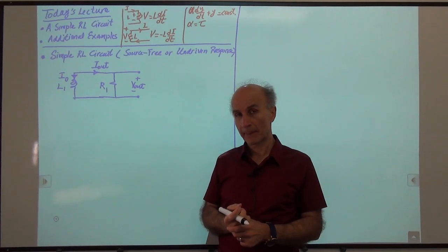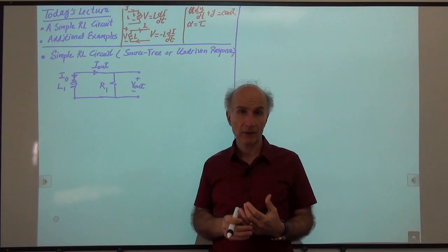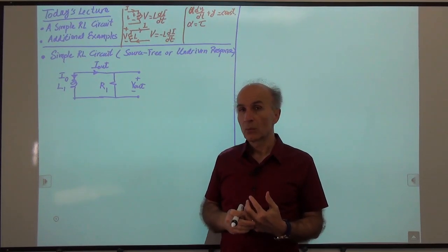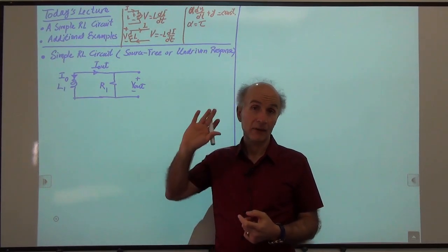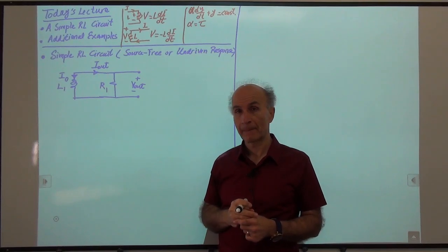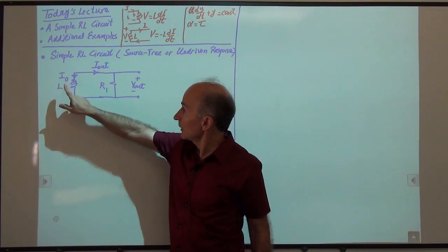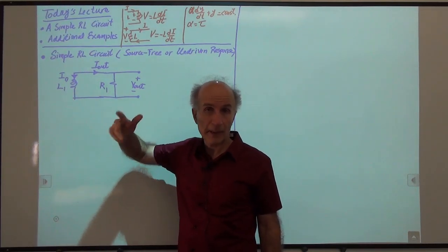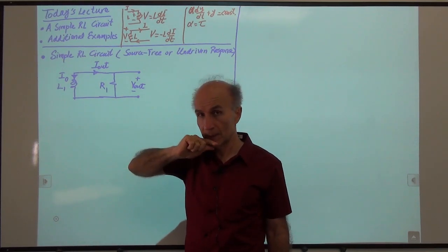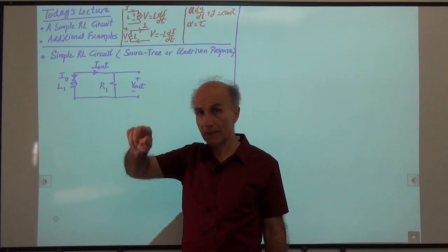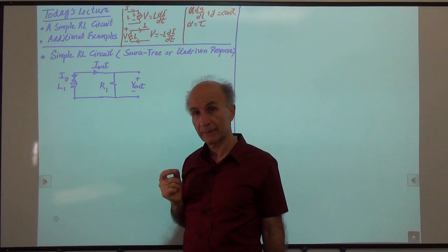All right, okay. So, again, before we jump into the math, let's ask ourselves, what do we expect V out and I out to be at time infinity? Well, what we can think is this. This initial current through this inductor gives this inductor some energy. 1/2 L1 I0 squared is the energy stored in this inductor when we begin to look at the circuit.